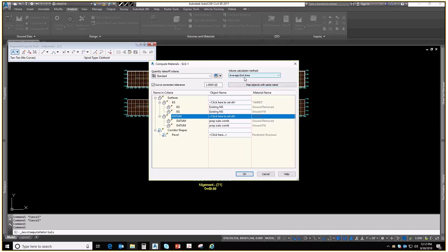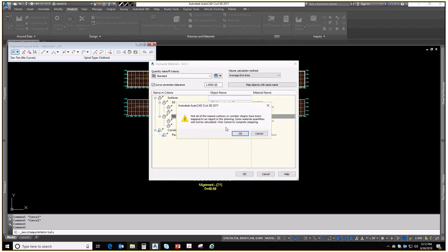Okay. So this is going to be the average end area, what we're using. We have never really used these. I'm not sure if Ken has anything he wants to say about those two, but average end. Screen is too small for me to see what they even are, Joe. Composite volume and prismoidal? Yeah, because of our bias to the ease of checking, I think average end area is about all we've ever used. Yeah. All right, so then you just hit OK.